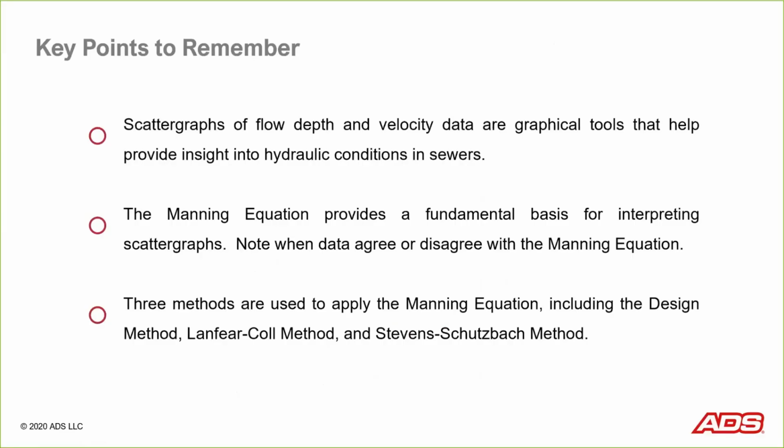And to help us understand that, it's important when we're looking at a scattergraph to understand what ideal flow conditions are like. That's expressed by the Manning equation. And it turns out that that equation is fundamental to understanding and interpreting scattergraphs.